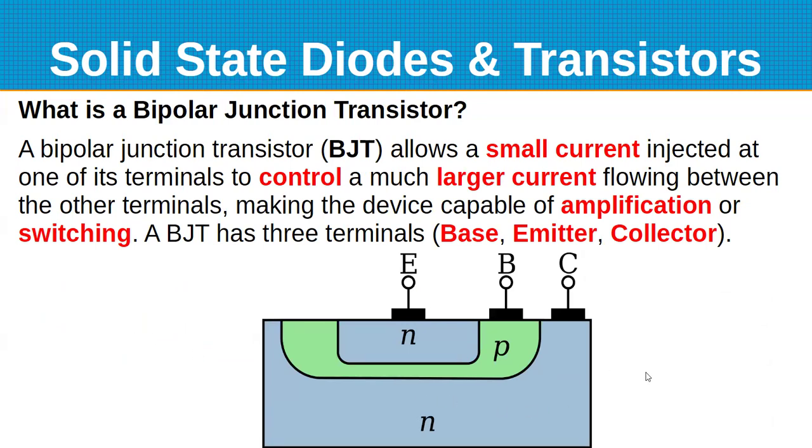This is a kind of a slice of how a typical bipolar junction transistor is formed. So here we have your diode with your PN junction, and then this collector is formed around it. Actually, they have the collector material, and I don't actually know the process, but they embed these other two within it and then make the connections. These are actually done most of the time with very fine gold wires that are welded onto these sections.